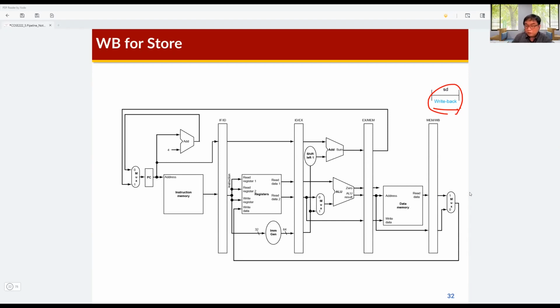One student actually posed a question on Piazza. The load instruction requires all 5 stages of the pipeline, but some instructions, such as R-type instructions, do not require the memory stage. That means we can complete these R-type instructions using 4 stages of the pipeline, and complete the load instructions using all 5 stages.